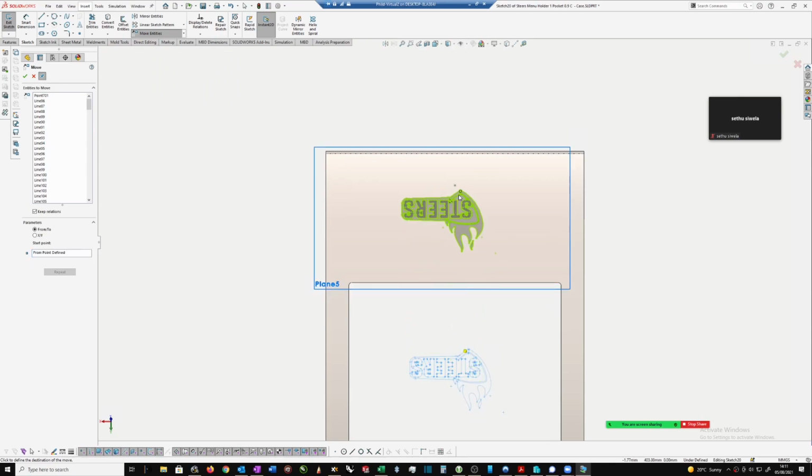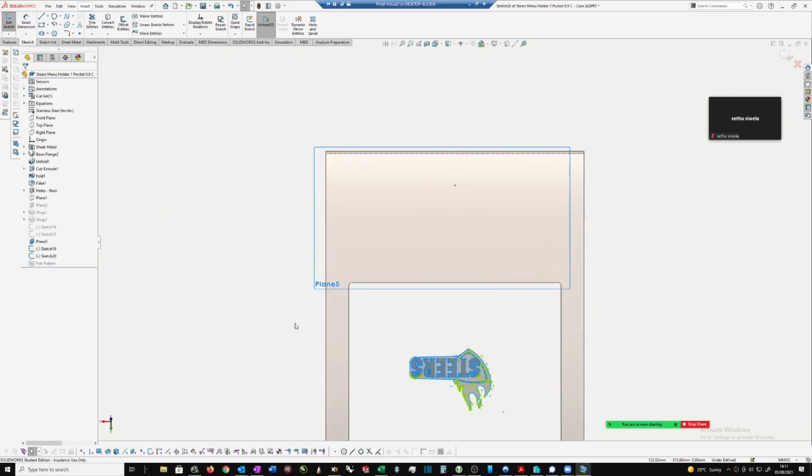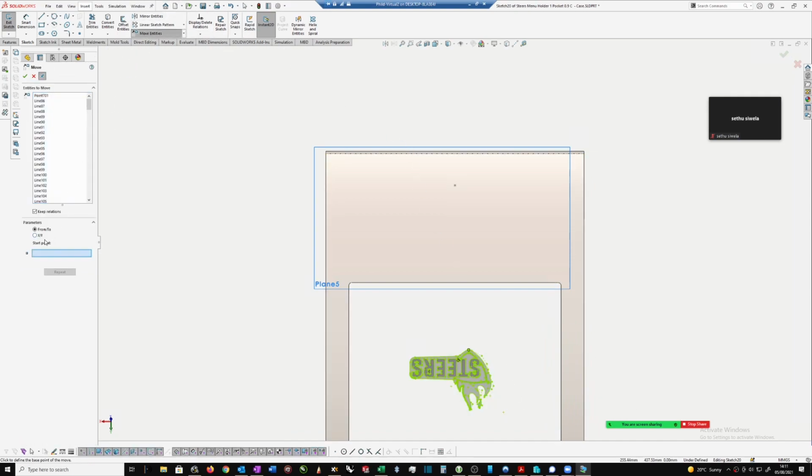Okay, so if you have problems dragging it, because if your computer's slow, this might get very laggy, then instead of doing what I've just done here, you can just select everything, move it, and then select the X, Y, and then go to Y and type in your dimension here, 132, and it is actually, yeah, that should be right. You can hit enter, and it won't exit the command. So if you need to move it some more, you can.